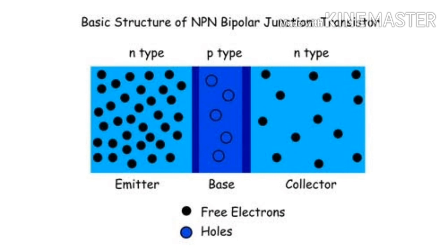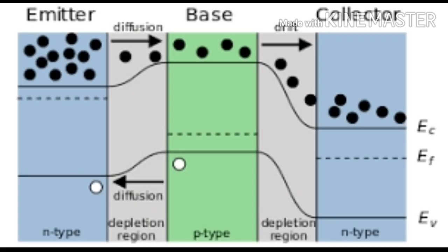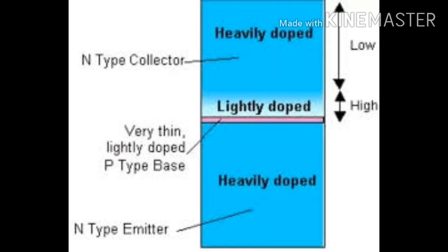So you can see that a transistor may be regarded as two junction diodes joined back to back, like one in emitter and base junction and another one in the collector and base junction. So there must be two depletion layers in these two diodes, but the two depletion layers must be of different width because the doping levels are not equal in emitter, base and collector regions.